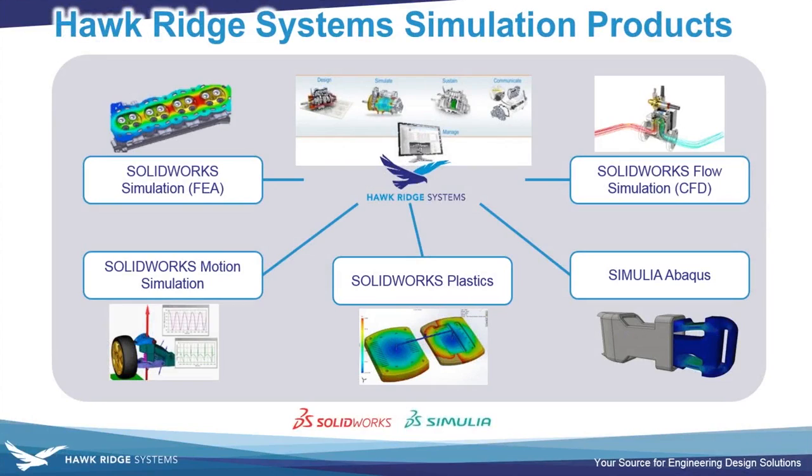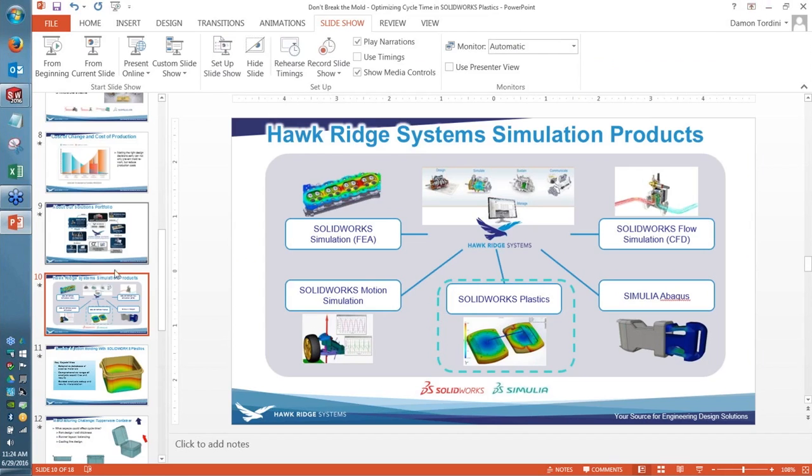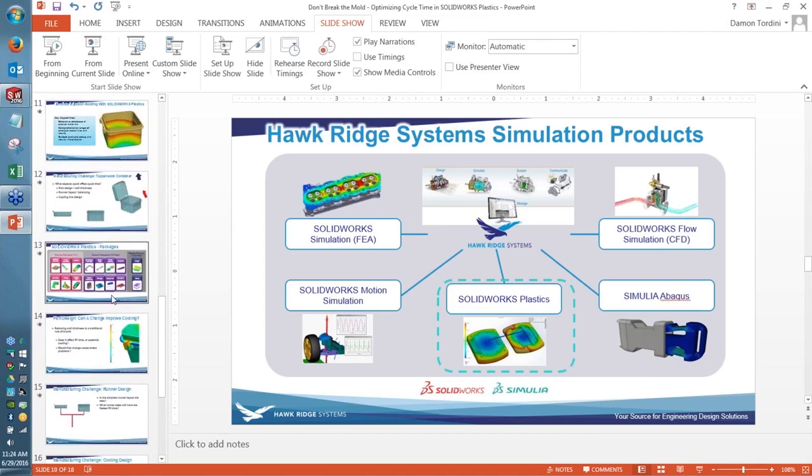Maybe just a simple static analysis of, let's say, a force on those hinges. And I could make sure that even if I cut that slot out of material, they don't bend too much. And I don't have to export my model or go to another program or prepare it for some other kind of analysis. I can do it right inside the same interface right when I make this change. And so once I've verified that the stress side of things is going to be fine with this change, now I can go back and see if it makes a difference in the injection molding.